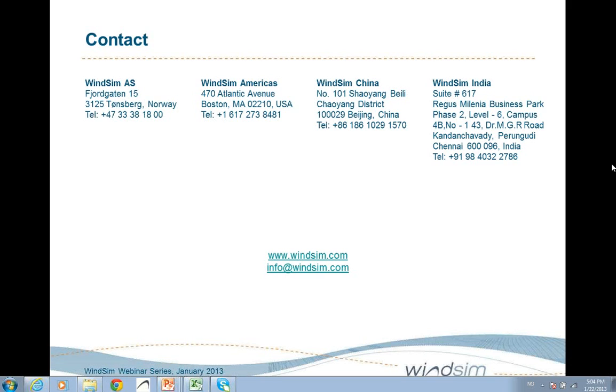So let's say if your really high resolution extends 2 to 3 kilometers in each direction away from the turbines, they should not affect the WindSim results too much. Of course, the SRTM has only a resolution of 90 meters, so this is not thought to deliver completely nice results in the turbine surroundings.